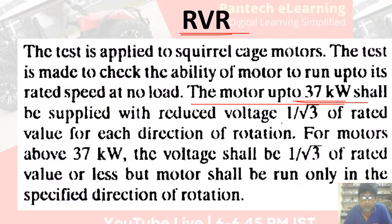Normally 1 by root 3 times the rated voltage will be applied, and if it is a bidirectional motor, it will be rotated in both directions. If it is a unidirectional motor, it will be done for that direction, and we have to look for any abnormality of the machine. So this is called the reduced voltage running up test.